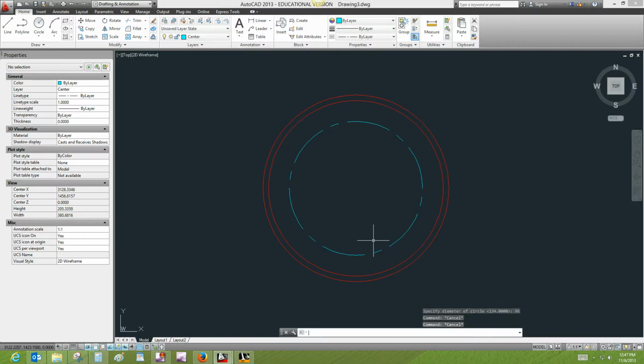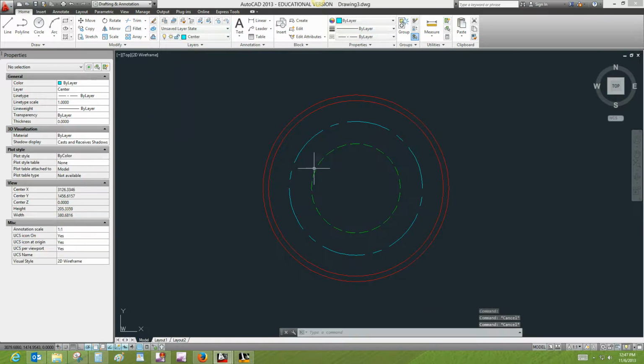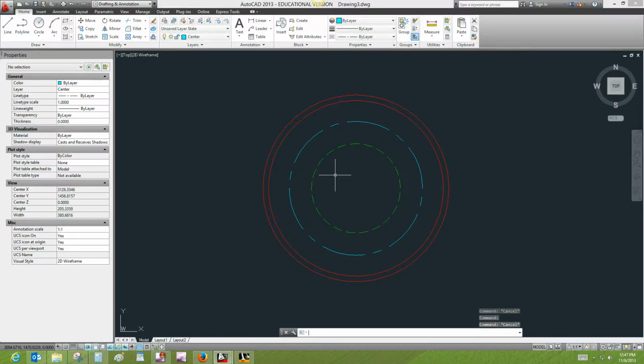We also have a hidden line in there, but we're not specifically given dimensions for that hidden circle inside. But we can see from the right side view that circle has a diameter of 64. I drew it on the wrong layer, but I can select it and then select hidden, and now it's on the correct layer. So double checking my measurements, diameter of 96, and this should be a diameter of 64. Now let's get back to what I was going to do and create the counterbore.